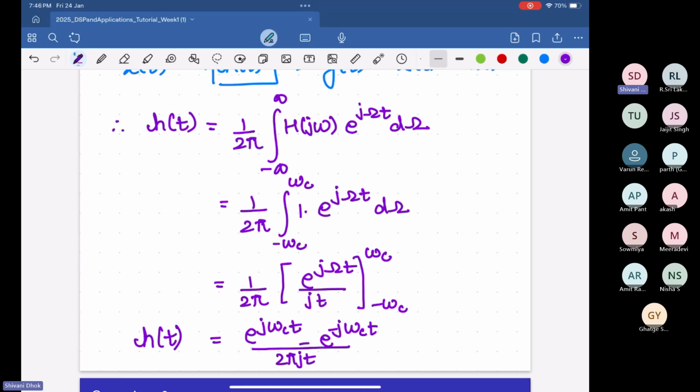Now, suppose you want to amplify, let's say you want to double the amplitude in that frequency range, then you can set it to be 2 in that region. However, when I just want to design a filter that passes those frequencies, and neither changes its amplitude nor its phase, in that situation I need to keep the amplitude as 1. Does that answer your question?